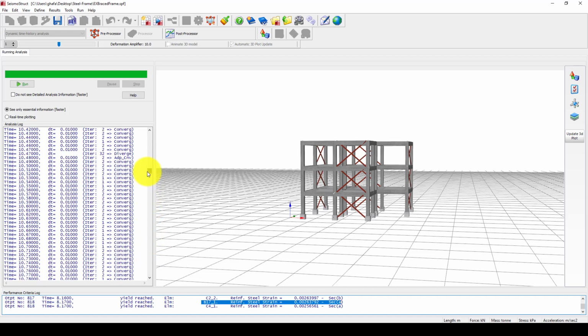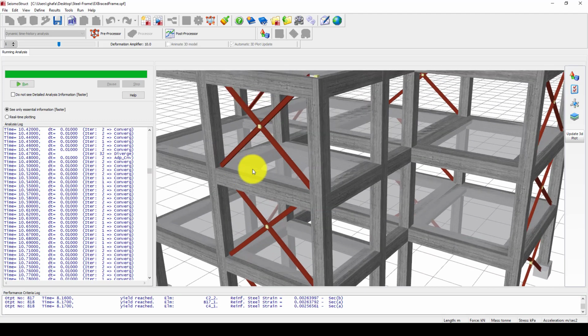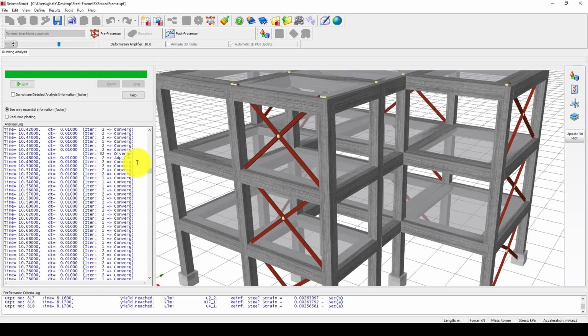Regarding the previous notification which we got at the moment of releasing this point, they said maybe they will not converge. Yes, the program is trying to use multiple iterations. It reached iteration 32, which in the setting was 100. In that specific step, between 0.1 and 0, it didn't converge. Even though the iteration reached 32, it's called divergence.